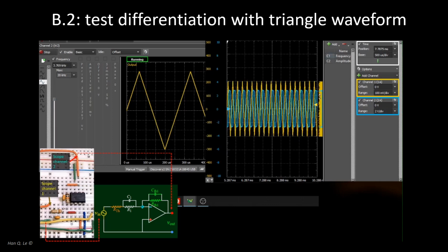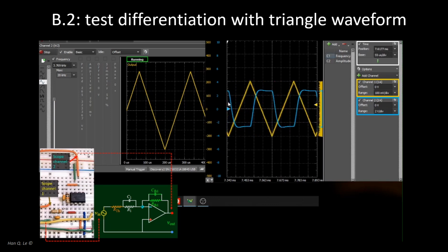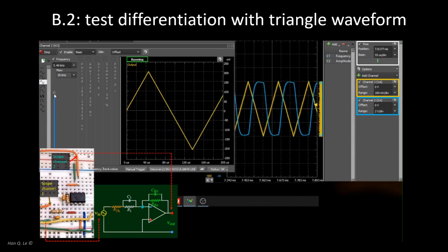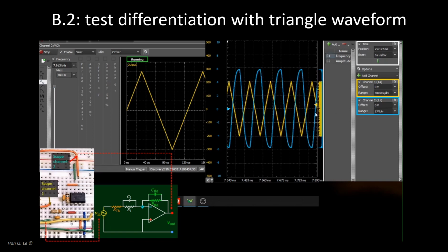On the fast time scale, or high time resolution, the square edge shows roll-off, limited by the op-amp bandwidth. The damping capacitance introduces near-critical damping and reduces the underdamped oscillation. Higher capacitance would make it overdamped. One can pull out the damping feedback capacitance to see the oscillation.